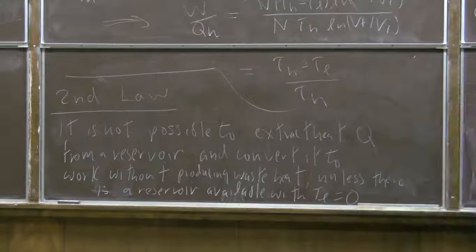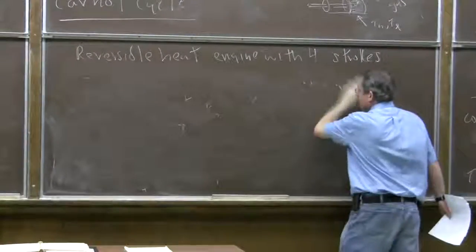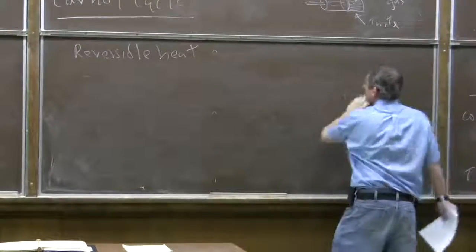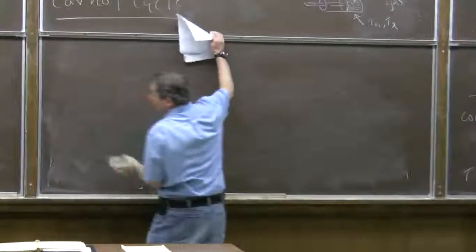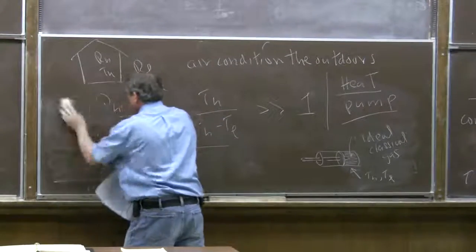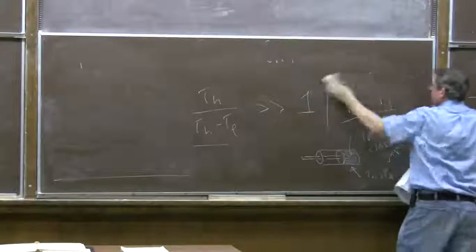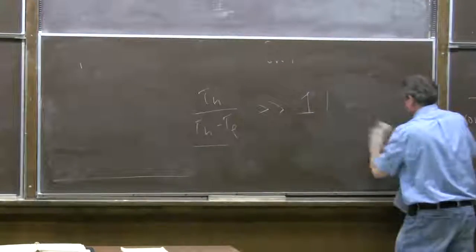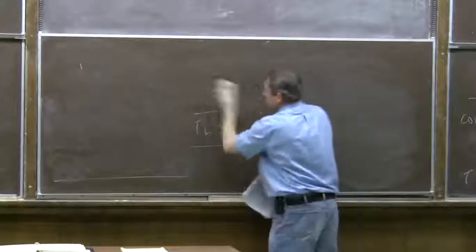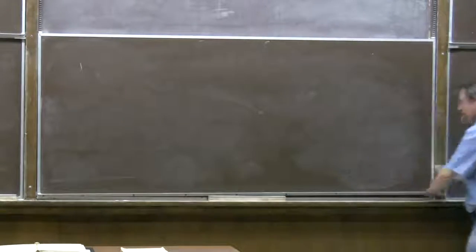Now it's kind of an interesting observation that it follows just from that statement that all heat engines or refrigerators that operate between reservoirs with given temperatures, tau H and tau L, which are reversible, have to have the same efficiency. So there's some universal efficiency, which we've seen follows just from the requirement that the entropy stays the same, the Carnot efficiency.